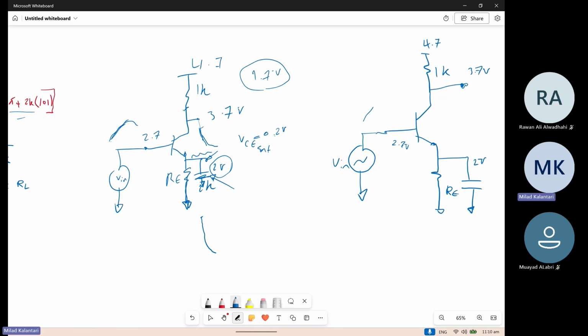The base voltage is increasing, the collector current is increasing, and then this voltage is decreasing, right? And then the ratio of the increment is like the gain, right? With this value of the gain, this starts dropping, right? So I just try to plot the time domain, the VCE of the device, basically. So first of all, the emitter voltage does not have any AC variation. Why doesn't it have?